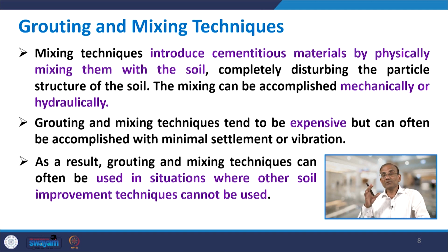In grouting, you are not disturbing the particle structure of the soil, but in the case of mixing, because you are mixing physically, it gets disturbed. The mixing can be accomplished mechanically or hydraulically. Grouting and mixing techniques tend to be expensive, but can often be accomplished with minimal settlement or vibration. As a result, they can often be used in situations where the other soil improvement techniques cannot be used.